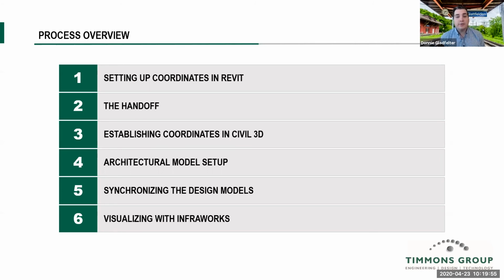Once everything is synchronized up, this is where I think the real fun begins, because we can begin exchanging the Revit model into Civil 3D. We can also begin taking those critical elements from the civil design and export them in a format that Revit can read. You might recall that the big thing we used in that coordination was the Site Designer add-in that we can get free from Autodesk. While a lot of the tools aren't so useful, the one that is super useful is the Import Land XML tool, because that will allow me to import the exact surface as it exists in the civil model into Revit.